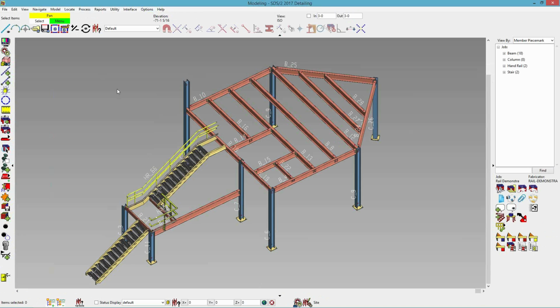The first one I'm going to cover is the add flat rail. This currently only works for flat handrail. You can think of this tool as the quick add for handrail, which is similar to the stair quick add. I'm going to pick multiple points to add my handrail, but once it is complete, they will be separate handrail members just like the stairs. The add flat rail allows the user to quickly and efficiently locate the path of the handrail. Then you can come back and make modifications as needed for the individual handrail.